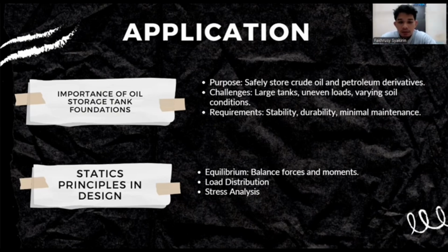Dynamic loads arising from tank filling and emptying also need to be accounted for. Stress analysis, particularly focusing on hoop stress in the tank walls, stress concentration around the base plate, and soil pressure distribution, is critical to avoid foundation failure and maintain the integrity of the storage tank.